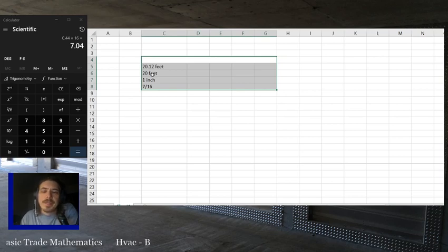And the other thing is if you are working on load calculations, when we talk about Manual J, and we learn to do load calculations using the abridged edition, which you guys have, which is all done by hand. You don't want to actually do the whole thing by hand. It will take you absolutely forever. They have Excel spreadsheets that you can use, and it's even simpler than doing this because most of it's already in there for you. You just have to change the numbers around.